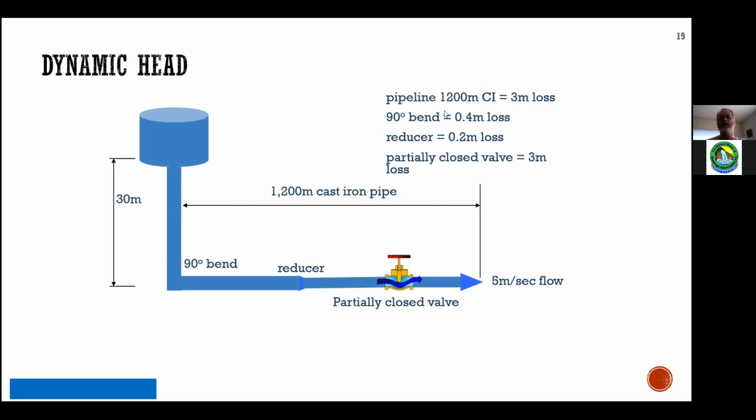And we say, okay, we can actually calculate, and you won't be asked to do that, but engineers do, through tables based on the size of the pipe, the material of the pipe, and the degree of the bend. And of course, the higher the energy, the more there is to lose of it as well.